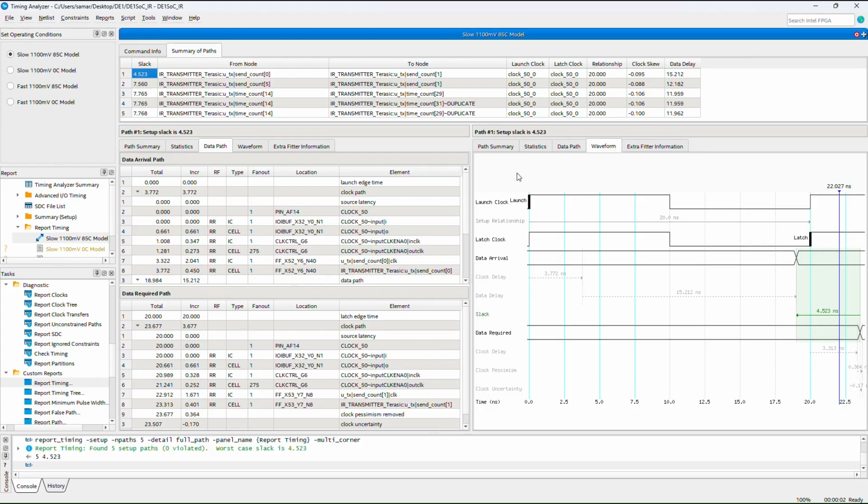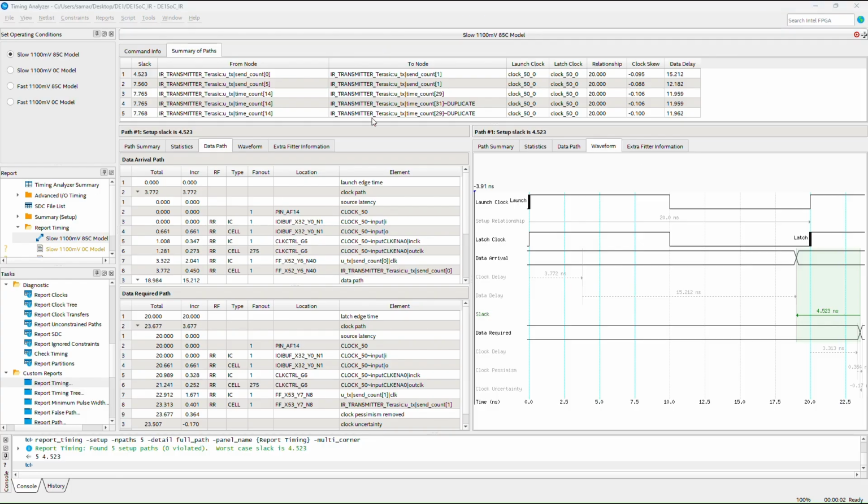Now let us go ahead and dump the same program onto our FPGA. While dumping this, I'll be using the .bat file, which is basically a Windows batch script. Instead of opening it in Quartus as we were doing before, you could basically run that, and that directly checks if the JTAG matches, the kind of board we are using, and the .sof file. So let me show you how that would work.